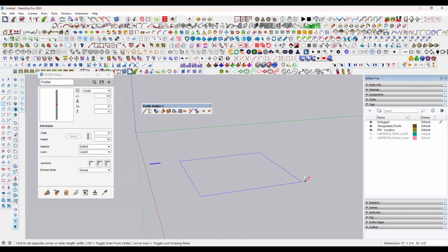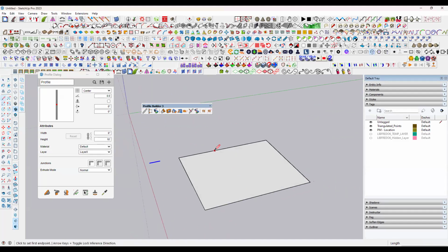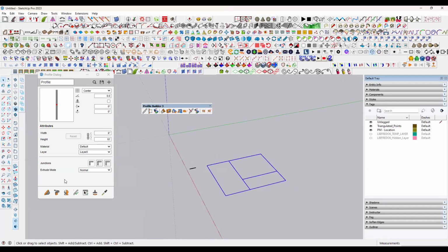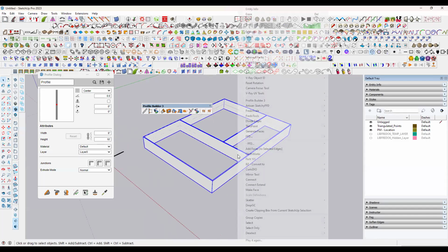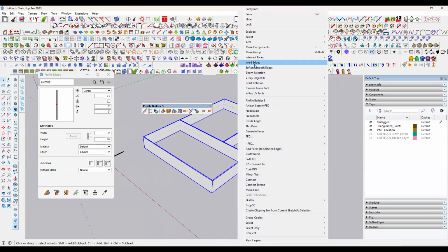So first, even if you have a 2D now, let us say these are my 2D lines. On the 2D, I'm selecting all the lines here. I can directly click on it and create walls directly. Then I can just give a right click and go to the solid components, solid object. I can make it a boolean directly.